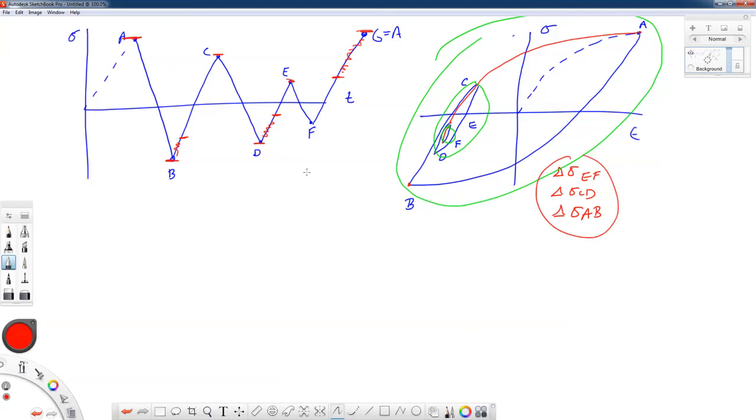So I prefer to develop a rainflow cycle counting algorithm in terms of logic, looking at the time history. But the reason why it's called rainflow cycle counting is if you were to take this time history, sigma versus time, and rotate it by 90 degrees, maybe I can make a copy of that and show you here. The original developer of rainflow cycle counting was a Japanese researcher in fatigue analysis, Endo.